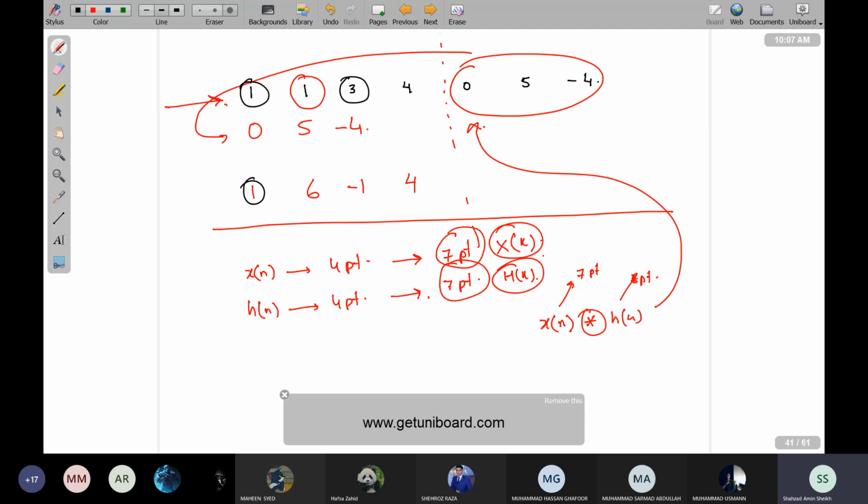So in order to make circular convolution give you the result which is equivalent to linear convolution, which is our requirement, you will pad extra zeros to your original sequence, and as a result of that circular convolution, you will be getting your result which will be equivalent to linear convolution, which is the actual requirement of ours. Questions, Peter?